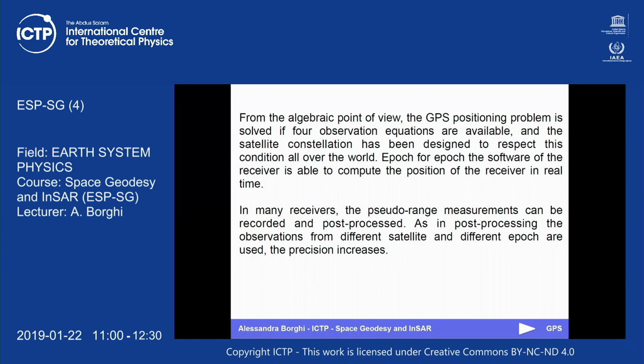Now we increase the rate, and we also use 1 second or less, because we have seen that with the GPS I can have information also about the seismic waves in case of earthquake. So the improved technology allows us to improve the rate frequency. So these are the epochs where I have data, and if I don't need real-time positioning, I can use more observations. I hope not to confuse you with this.